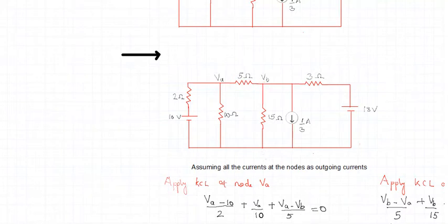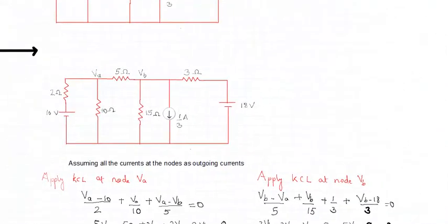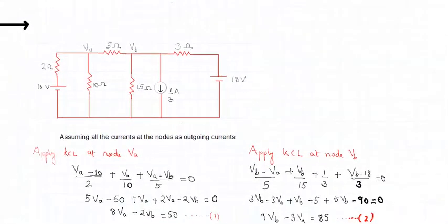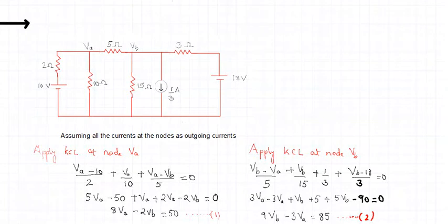Right, so if I apply the definition of KCL, what is the equation we get? Let us identify once again. So VB minus VA upon 5, right? You could see here VB minus VA upon 5 is the first branch. Now this particular branch is VB by 15, correct?